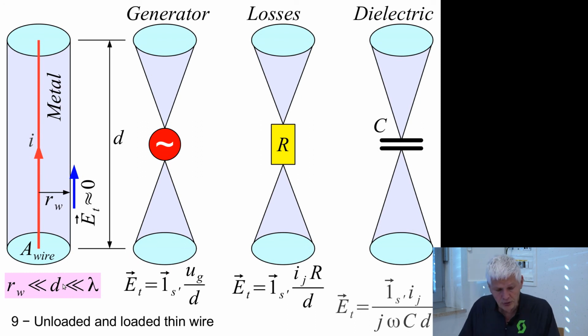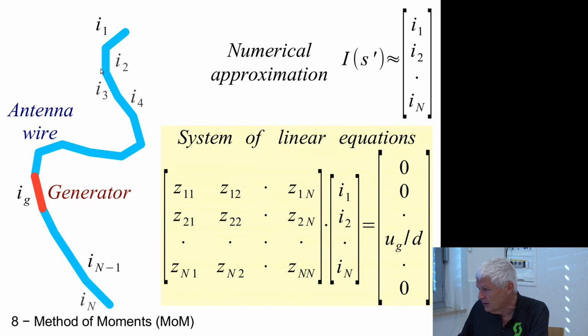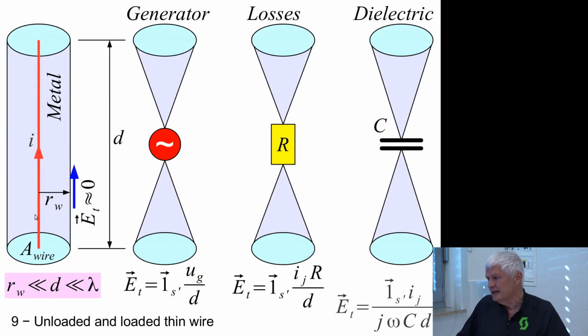We can also put other things inside our segment. So we said that most of our antenna is wire of good conductivity, say a metal that has almost 0 resistance. But we may have a generator somewhere. How do we install a generator here? We install a generator inside a biconical line that has some defined behavior, some defined characteristic impedance. And this biconical line adds up exactly at the ends of our segment. So this is the way to put a generator inside.